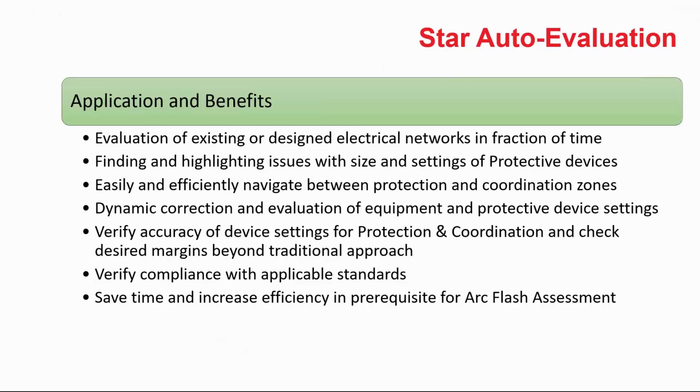You have the option either to dynamically correct your evaluation results, applying the protective device setting changes dynamically, or if you wish for a larger project, you can use the static correction, do all of the correction in one shot and then apply it all at the same time. It would verify accuracy in the device setting for protection and coordination, proximity check, the margin, everything that you need in preparation of any report is provided in the tools available in the software. It will also verify the compliance with applicable standards, as I showed you in the rulebook, standards such as the NEC rules and articles.